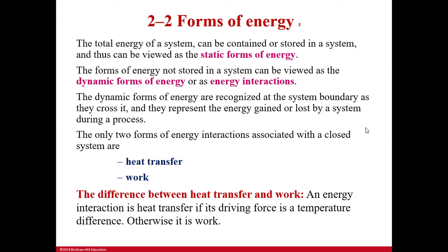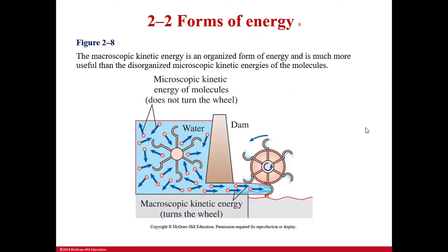The difference between heat transfer and work: an energy interaction is a heat transfer if its driving force is a temperature difference. So remember, that energy interaction is heat transfer. That means heat transfer occurs because there is a difference in temperature between two places, right? Otherwise, it is work. Work is also energy transfer. Heat transfer is also energy transfer, but heat transfer occurs because of a difference in temperature between two places.